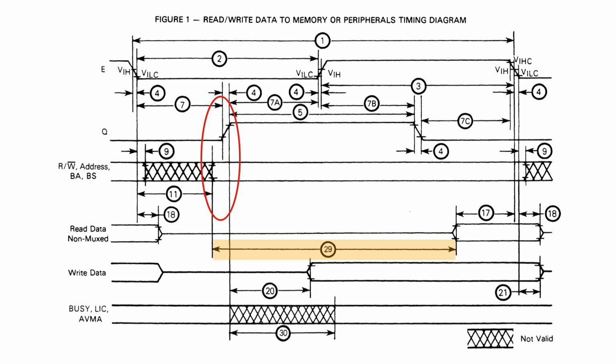Specifically, it allows me to use 74AHC series logic ICs, which are typically faster than 74LS chips and consume a lot less power. So because of this base propagation delay of 9.5 nanoseconds, I need to avoid having multiple stages in my address decoder, where the later stages rely on the result of some other prior stage, because having those would cause those propagation delays to kind of stack up.